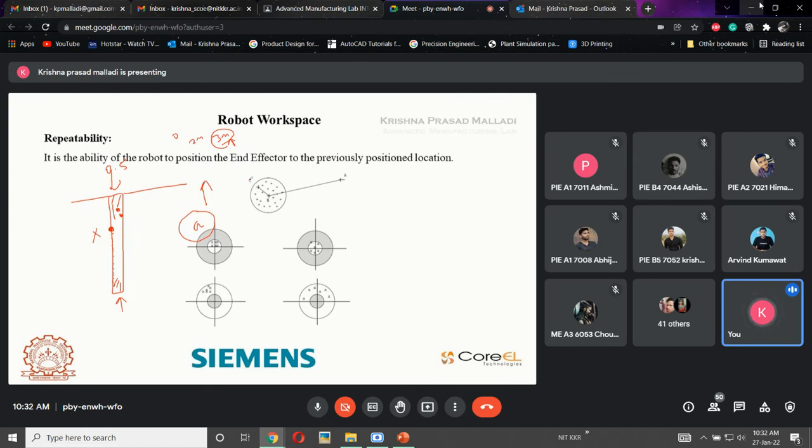So what will happen here? What is the length of this one? This sheet length is 0.5 centimeters, which means 5 mm. So this is 5 mm and the maximum spot is 3 mm. They are going to take this 3 mm and this 1 mm here and 1 mm here as tolerance, which means even if the weld comes to this 1 mm, 1 mm, it is acceptable, but beyond that it is not acceptable. This is how they prepare the program. They are going to maintain this ratio. That is why this plays a key role. Clear?